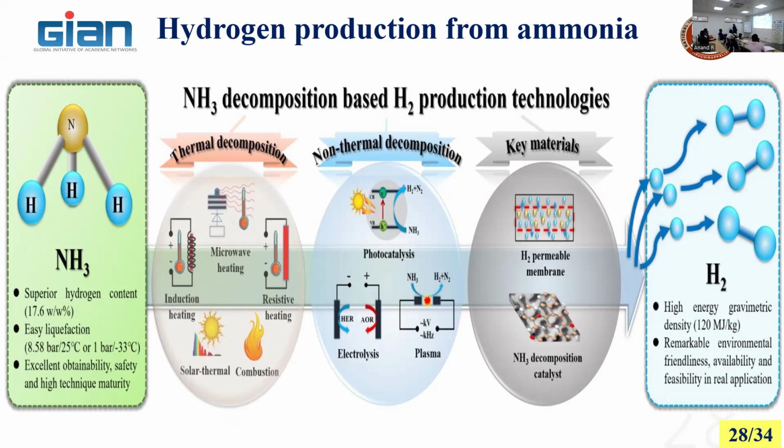Another option is to make use of a membrane impregnated with the catalyst. You can also decompose the ammonia into hydrogen that way. Hydrogen is high in terms of mass basis; it is the highest calorific value fuel, but in terms of volume basis, it's the poorest. Ammonia has an average calorific value when compared with petrol oils.